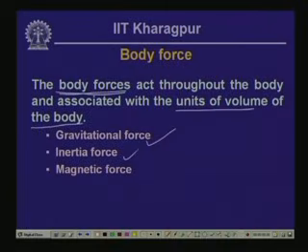Though it is distributed over the volume, when we try to analyze the forcing system, we apply the body force assuming that it acts through the center of gravity of the body. So, when we analyze a particular structural component, the body force we apply at the center of gravity of the body, and basically these are the gravitational force, the inertia force or the magnetic force, generally termed as the body force.